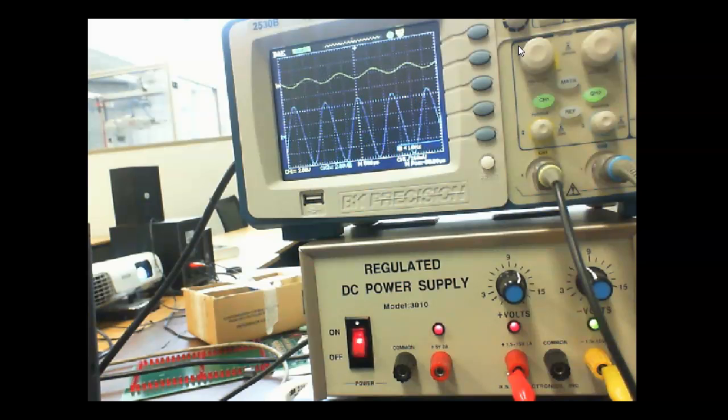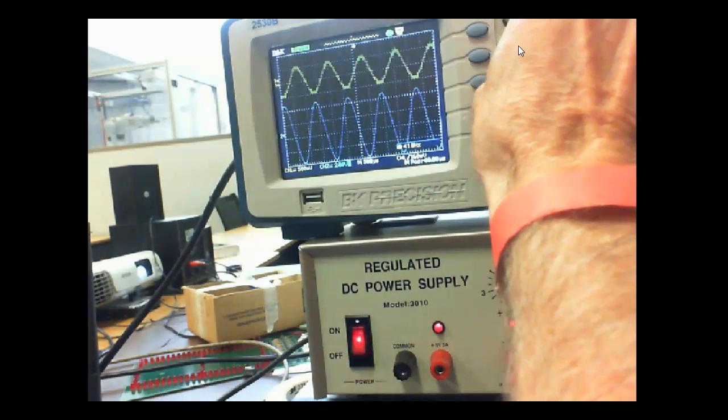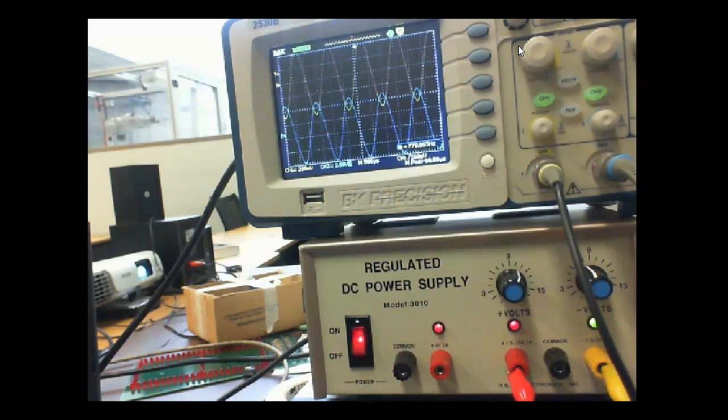So normally when we go through stages of amplification, we start off with an extremely small signal. So think about the voltage you're getting off the antenna of your car. And yet you're getting 30, 40 watts over on the other side, right? You understand? So we can't get that much gain out of one stage, right? So we usually go through multiple stages. And the output stage is going to use another range. But the only thing that goes on here is that your input and outputs are 180 degrees out of phase for this amplifier right here.